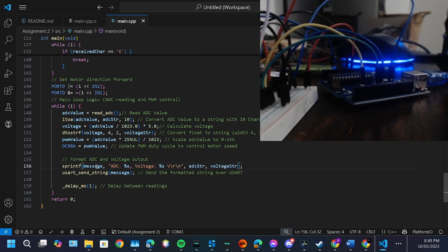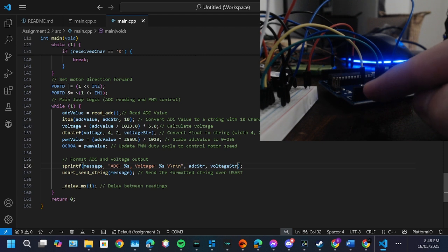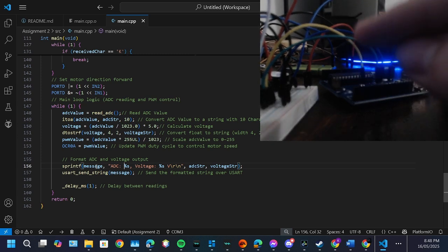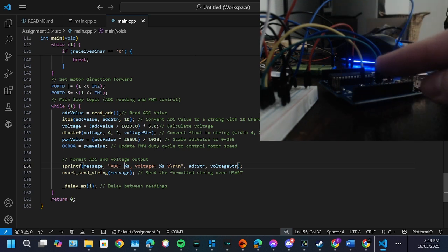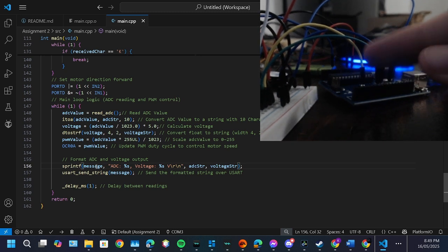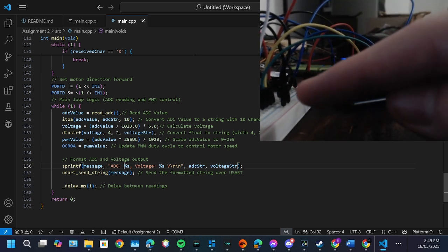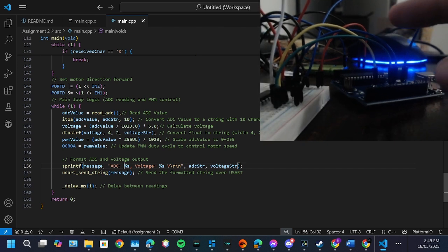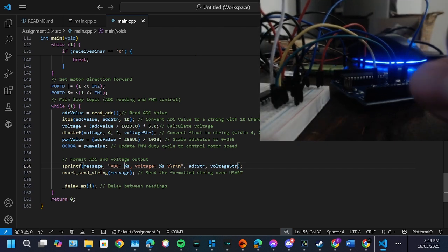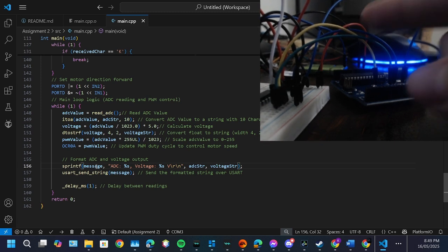Here's the Arduino. So for the pins, this pin here, which is digital pin 2, connects to input 1. This pin here, pin 6, connects to the enable pin of the motor controller, and we have pin 7 connecting to input 2.